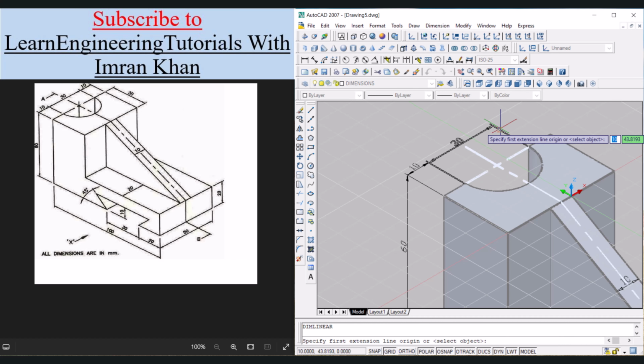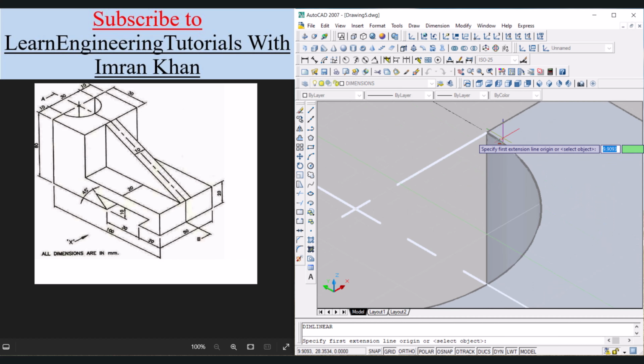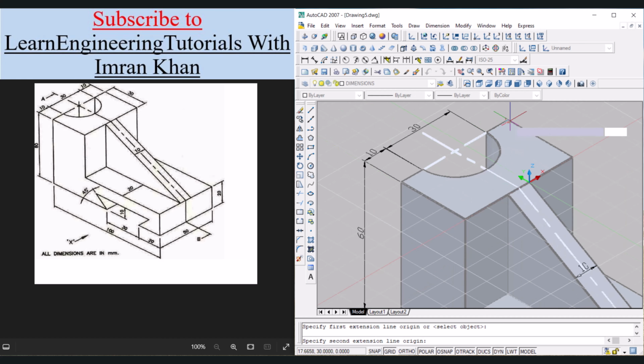Press enter, click on this endpoint, opposite endpoint and click. Press enter again, click on this endpoint, opposite endpoint and click. Now we can see that this 30 is inverted, so click on this 30, press delete.